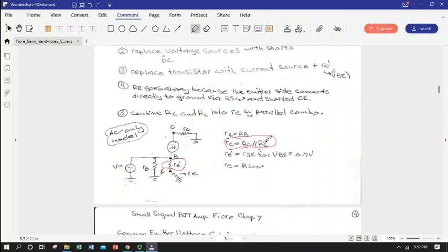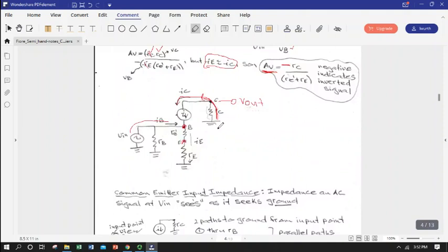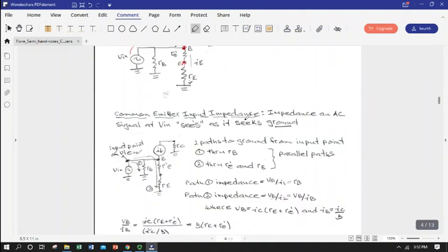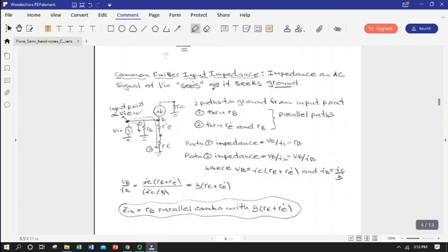If the load resistor were huge, like 100 mega ohms or something very, very large, it was input into a big instrument, then R sub L would be huge, and little r sub c would be mostly big R sub c. So we'd want to do that if we were taking a measurement, but if we were using this amplifier to, say, supply another circuit, that wouldn't necessarily be the case. We might have some current flowing.